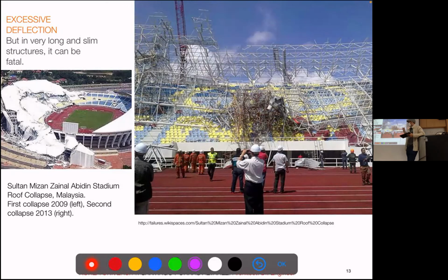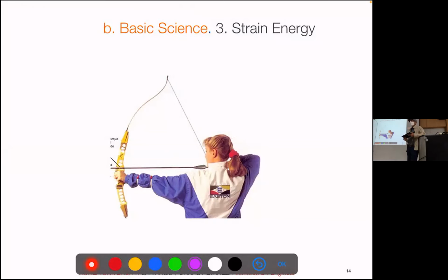We will speak about that later. Very strong, very slim elements have a tendency to bend, right? And to buckle, even if they don't reach their maximum stress. So much for elasticity. You can breathe. We went over it, thanks to Newton and Young, Euler, and all those guys.